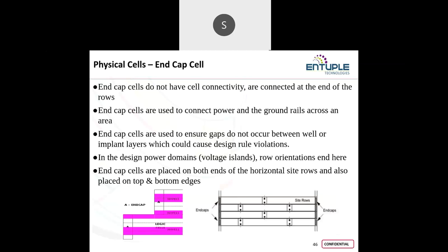To avoid that, I am giving a barrier to the design, or you can say the core area. Here in the pictorial representation, I am giving a barrier to the core, with the pre-cap and the post-cap, at the start and at the end. I am giving a barrier to the core area so that whenever I do the placement, all the standard cells will be placed within the core area. They will not move outside the core area.